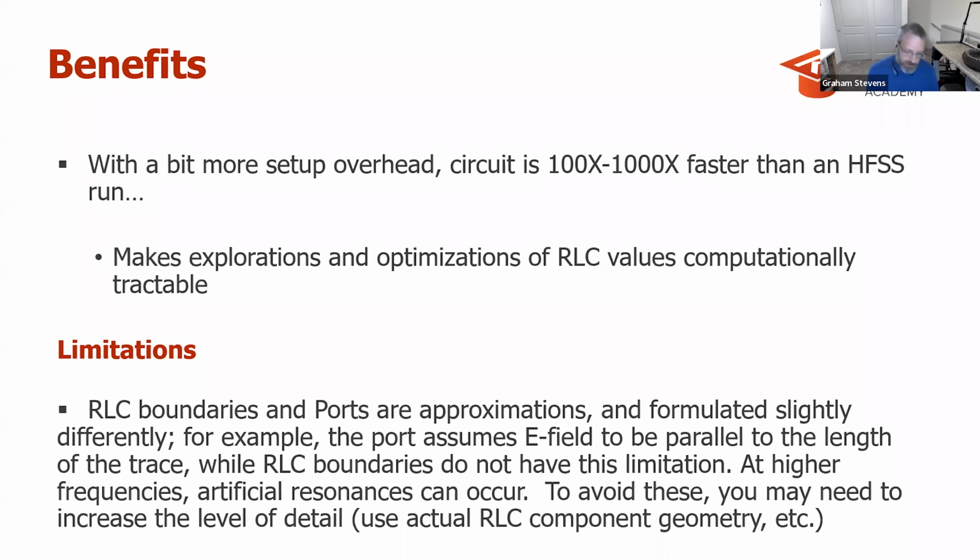So there are a few limitations. You never get anything for free. RLC boundaries and ports are approximations, and they're formulated slightly differently. For example, the port assumes the E field to be parallel to the length of the trace, while RLC boundaries do not have this limitation.